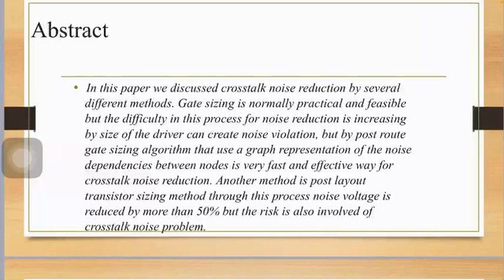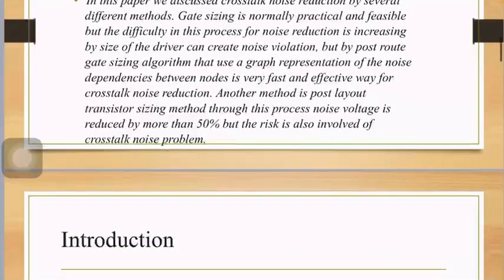Gate sizing becomes complex for non-linear circuits, and transistor sizing also becomes complex, but transistor sizing is done using graphical representations and a heuristic algorithm, which makes it easy. Almost 50% of crosstalk is reduced using transistor sizing, so this method is most effective.